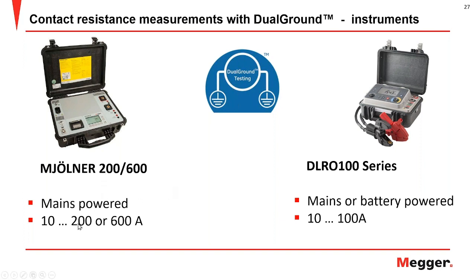The main difference is that the DLRO 100 is both mains and battery powered with test currents between 10 and 100 amps. The Mi is only mains powered with test currents up to 200 or up to 600 amps depending on the version. Both have quite a high duty cycle.